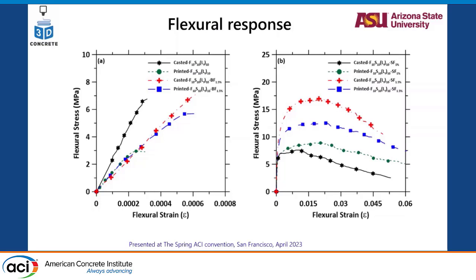So maybe we could use the fiber orientation in printing to our advantage. Maybe we can orient the fiber filament such that wherever we need the strength, we just orient. Let's say we want a truss, we want a tensile compressive response, right? So rather than being randomly oriented, if it is oriented along the length, it will have a better response.